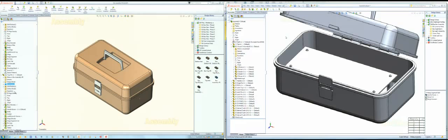And now if we ever have to edit it, we can edit that part. It's right here in the assembly. It'll update all the shapes of the multi-bodies, and that in turn will update all the shapes of our separate parts that we just used. Did you virtualize it? Well, I didn't virtualize it, but I turned it into an envelope. And then it doesn't appear on the bill of materials. And that's new for 2013 too. You can turn any part into an envelope, including a multi-body part.